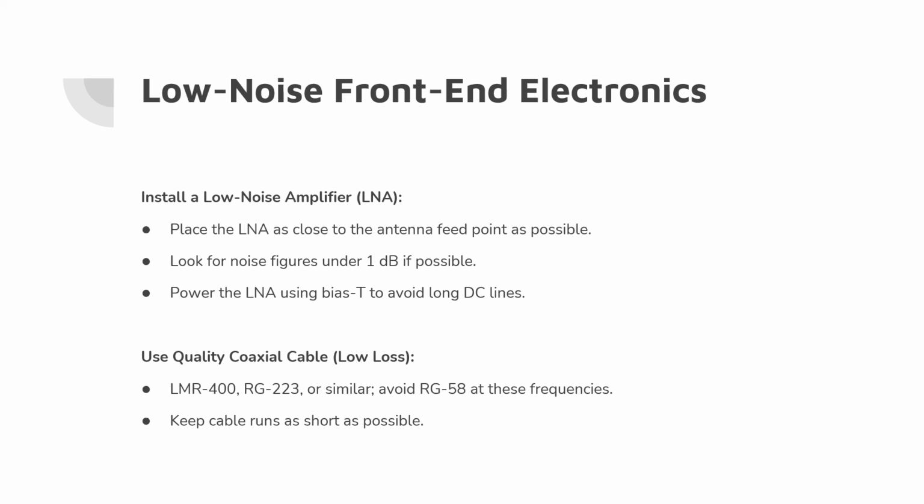And it's RG6, so I was planning on using the same cable. Hopefully it will work, because I don't want to make another run if I use that back dish. But yeah, at 1420 with any kind of significant run, you could easily get significant signal loss with bad coax. So I would think that's still pretty high on the list, regardless of where the LNA is.